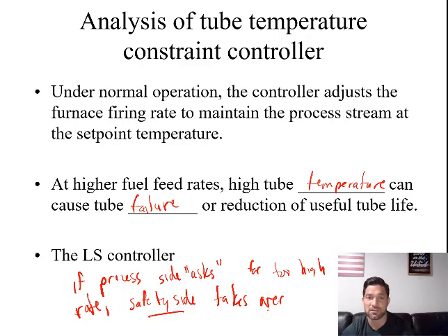A good example to look at for this would be preventing a tank from overfilling using the flow control at the inlet versus the flow control at the outlet. Because again, to prevent the tank from overfilling, you would have a different value to the manipulated variable if you were controlling it based on the inlet stream versus at the outlet stream.